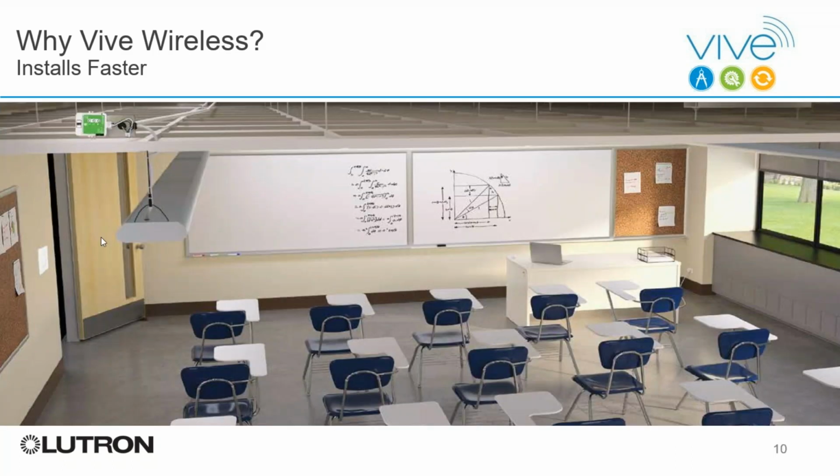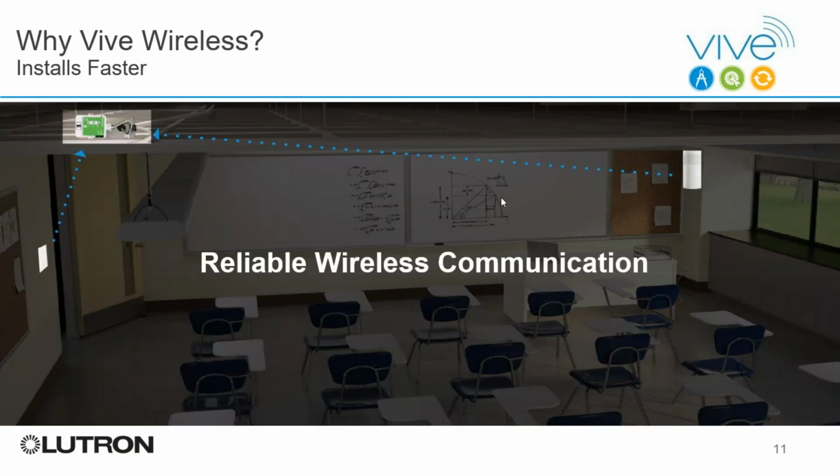To get an idea of how that looks in a room, typically with that wall switch on the left, you'd have to have a wall box and mud ring, and you'd have to run the wire up the wall with conduit or flex cable or whatever. You'd have to connect it to the lighting control module. Then from that, you'd have to run the wire all the way over to the sensor, either in the ceiling or on the corner, and put a power pack up there. There's a lot of wires going on. But with wireless communication, those are done without having to run those wires. And when you're talking about Lutron and Vive, we're talking about ultra reliable wireless communication.